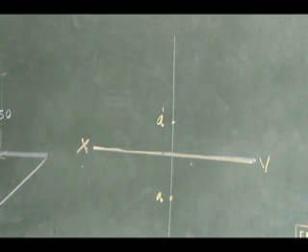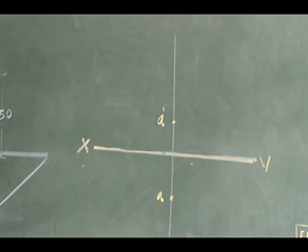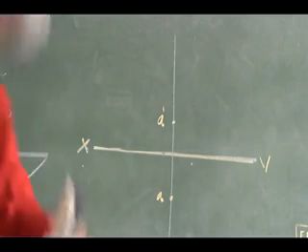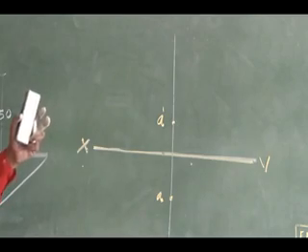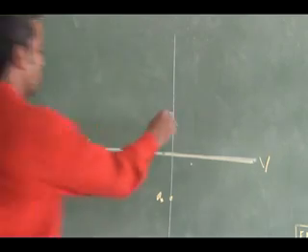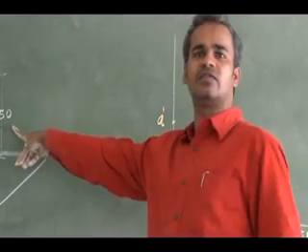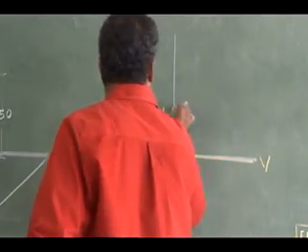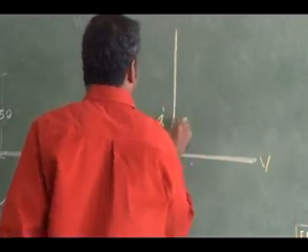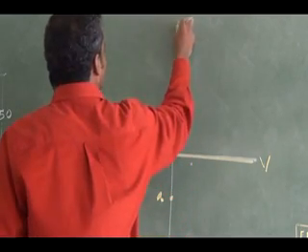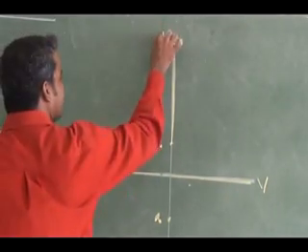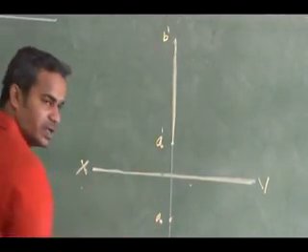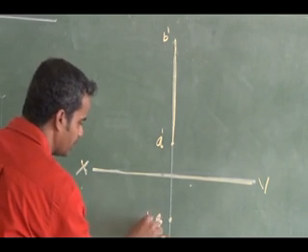Then you know it is parallel to VP and perpendicular to HP. So in VP I will obtain a straight line, true length, as the front view. So from here, for the length of the line, 50 mm, I can show the front view. So this is my front view. What will be the notation? It is B dash. Here I will have A and B together.